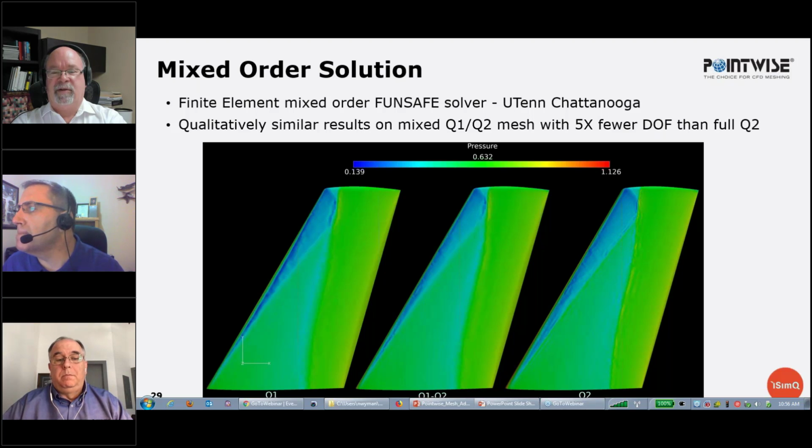Right. So in the CFD solver itself, the only thing that you need to make sure is that you're writing out the gradients in the result file of the variable you care about. They may already be there, but you may have to choose to force them to come out. Once those gradients are there, we have a process that sits in between CFX and Pointwise meshing, and that process really takes care of those first 3 or 4 slides you went through, coming up with the mesh sensor, and then boiling that down into a point cloud or set of point clouds. And really that's it. The interpolation is already there and built in. You don't have to do a thing for that to happen.